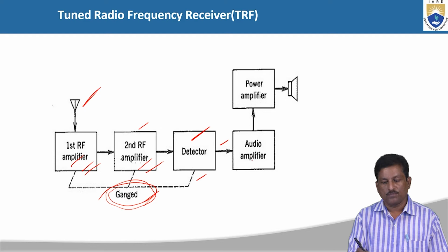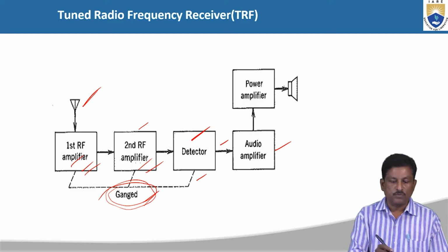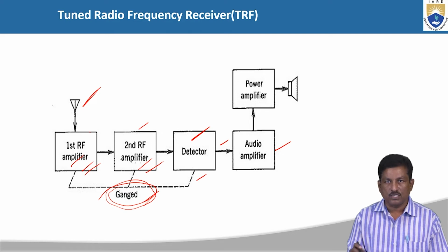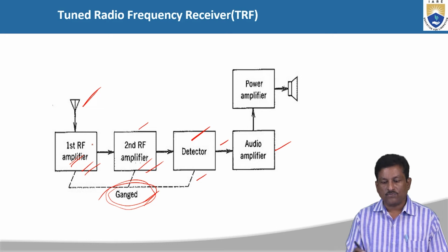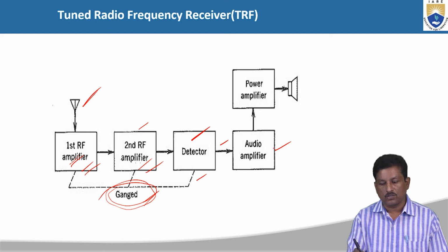This demodulated signal is a very weak signal. To increase the strength of the signal, we have to go for the audio frequency range amplifier. Whereas at the beginning stage, the signal received from the antenna is a radio frequency range signal, so we arrange a radio frequency range amplifier there. After the operation of the demodulator or detector, the detected output is an audio frequency, low frequency range signal, so we have to use an amplifier of the audio frequency range only.